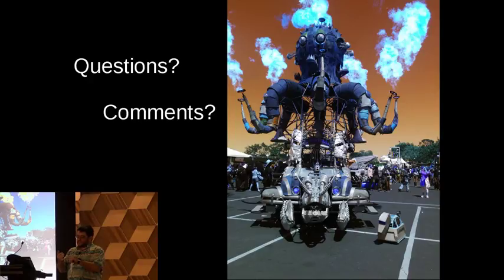It really boils down to being limited in how much storage space you have. The chip on here has 4 megabytes, which is astronomically huge in the embedded world. We were talking about one particular platform that had 64K of storage. You're not going to run MicroPython on that one, obviously. So your first hurdle is, can you even save the files to the device? The second is that you're RAM limited by quite a bit. You're talking kilobytes of RAM, not megabytes. If you're into the megabyte range, you're on a pretty expensive microcontroller.